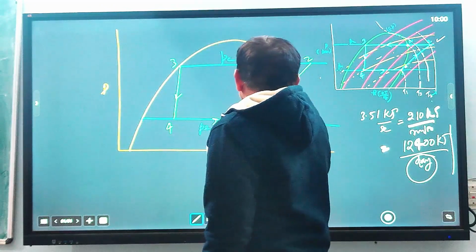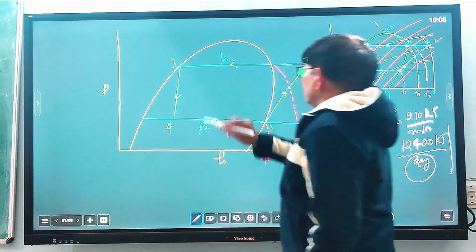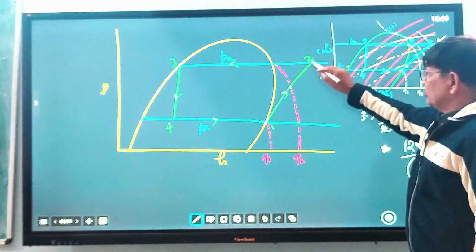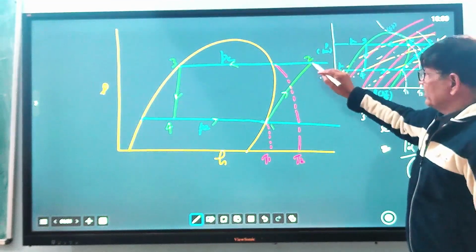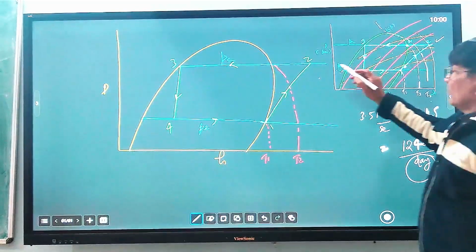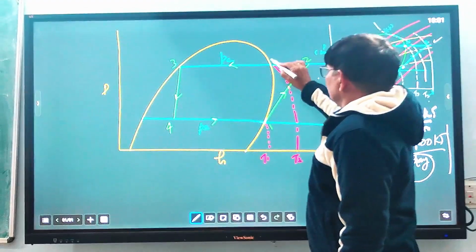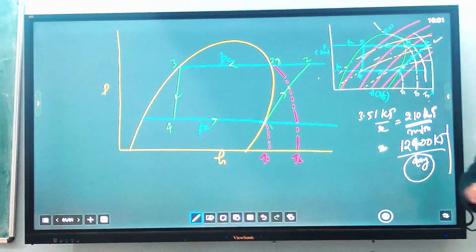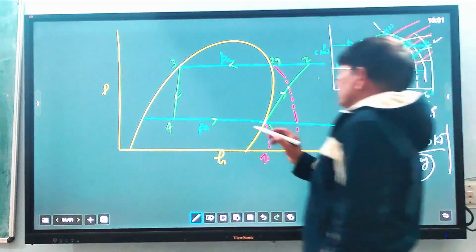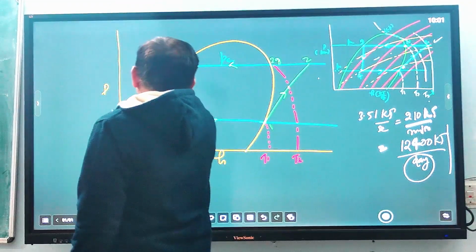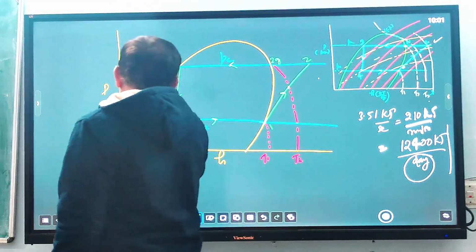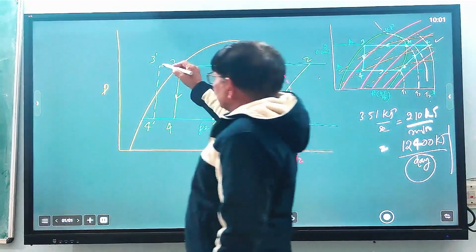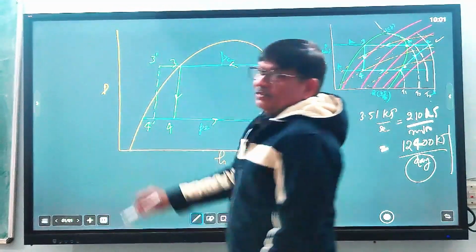Condition 1 means after evaporation, vapor enters the compressor at the fully saturated stage and after compression reaches the superheated region. I have just solved this question, and this is a gaseous state. So that is one cycle, and there is undercooling also. Take some undercooling, 3 dash and 4 dash. After condensation, further cooling takes place, so there is further reduction in enthalpy.